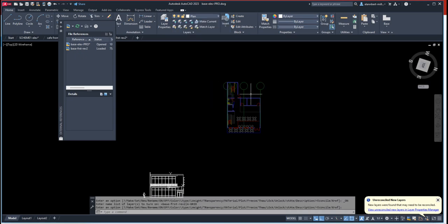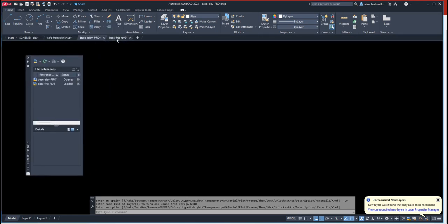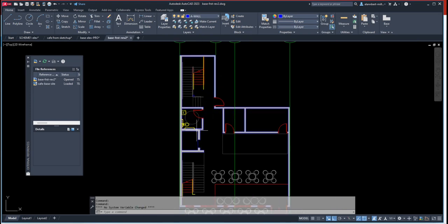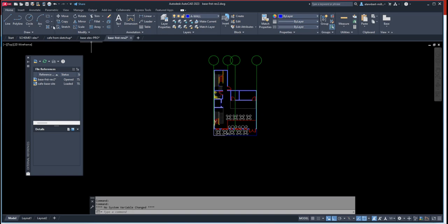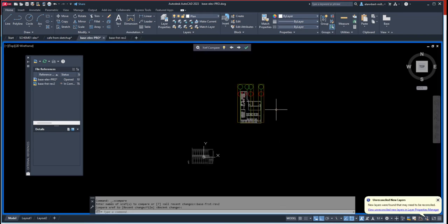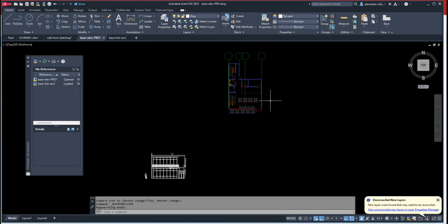If you haven't updated your grids, then you need to update them based on any changes that you have done. These are my new grids now since I added a wall here. I'm removing the grid from the elevator, and I moved up my grid over here. So I'm done with that one. I just click save. Then when I go to my base plan, it will tell me, hey, you updated your base plan. I simply click that, and it'll show me my updates, and I click check to accept those changes.